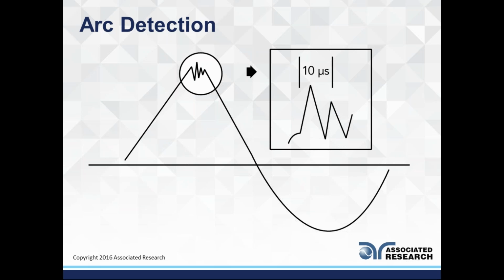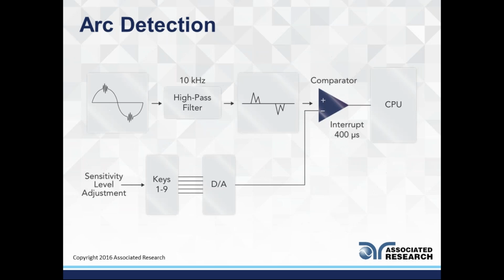And like I said, 10 microseconds. So this high frequency discharge occurs in 10 microseconds. So it's something that probably isn't going to harm a consumer like a Hipot breakdown would, but it can lead to breakdown down the line perhaps if you were Hipotting over and over and over the same device, which again isn't really likely, but just more information, more data for you to analyze when trying to understand the quality of your insulation. So how is arc detection handled?